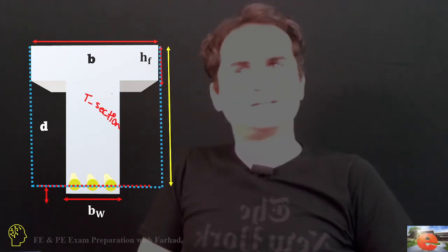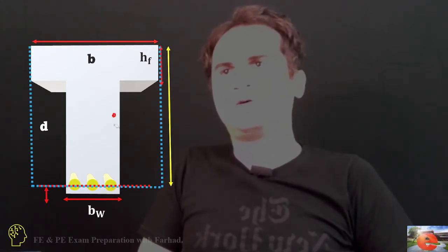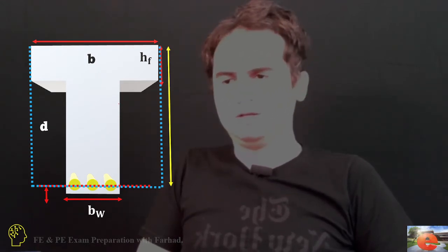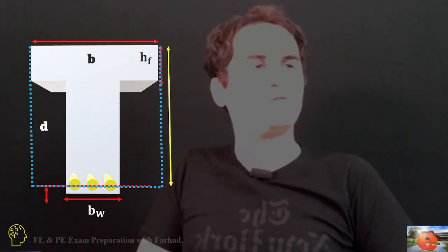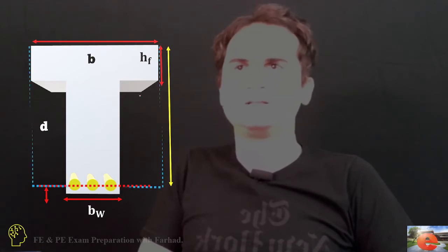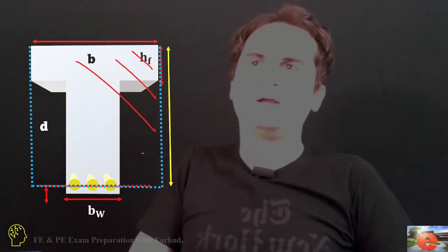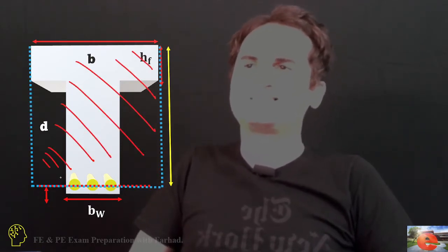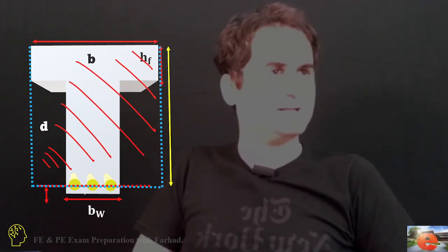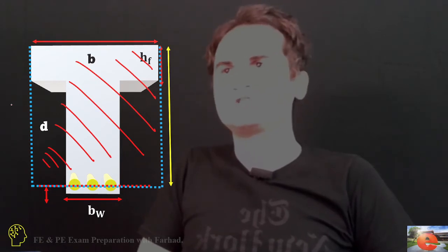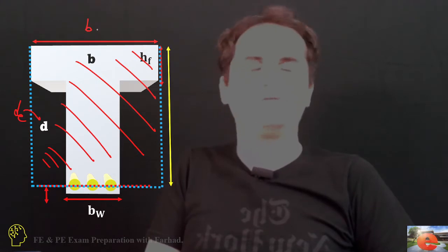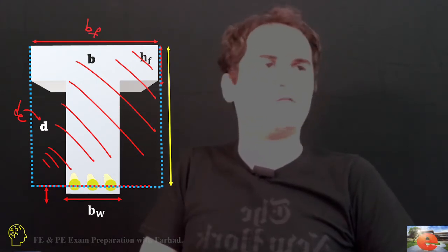The T-shaped section is very similar to the double reinforced concrete section. The very first step in analyzing a T section is to develop a simple rectangular section with the tensile steel at the bottom, with height of d effective and width b of flange.